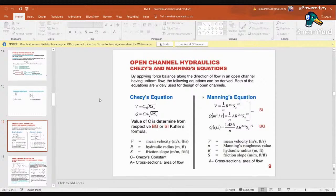Now, for solving open channel flow, we have two main equations, that is Chezy's equation and Manning's equation. By applying the force balance along the direction of flow in an open channel having uniform flow, the following equations can be derived. Both equations are widely used for designing open channels. Okay, Chezy's equation is V is equal to C square root of RS.